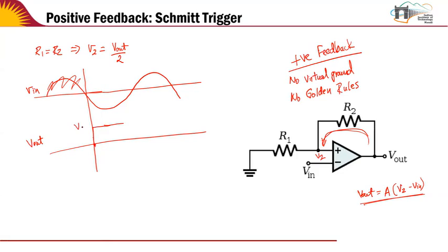Let's call this VCC, and the negative region minus VEE. These are the power supply values. So when the input goes negative, negative of minus V becomes a positive number, and therefore this whole quantity becomes positive Vout, and it goes to positive saturation. So it stays at saturation.